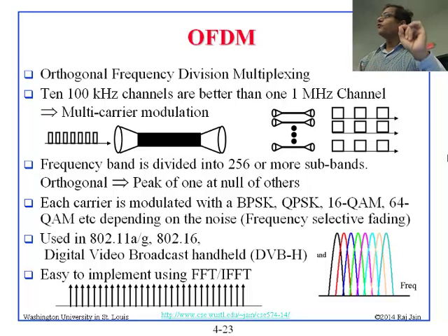So how many bits will I get through this channel? Channel number 1, 10 kilobits per second, right? And how long is each bit in terms of time? Now you just divide 1 by 10 kilobits, it's like 100 microseconds, right? So the bits are very wide.